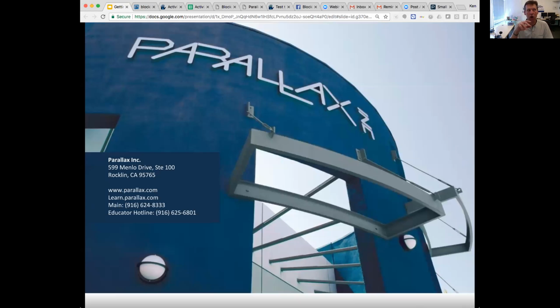You would actually have to open up the color blocks in another board type, like the Propeller Activity Board, then download them as SVG files, and then go into a Scribbler project and import those blocks. Then you would have access to the ColorPAL sensor. I haven't tried it, but I've seen one of our customers do all kinds of crazy things this way.